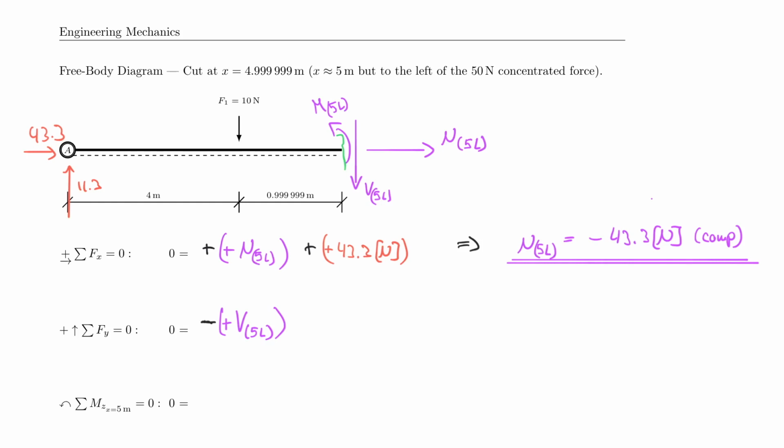And what's acting with it or in the same direction is the 11.3 Newton. And to be consistent, I also make that positive and put it in parentheses. But that is acting upwards, so I'm going up there. Last but not least, I have to consider the 10 Newton up here. So I also have a plus 10 Newton, which, yes, it's pointing downwards, but I indicate that with my negative here to be unmistakably clear.